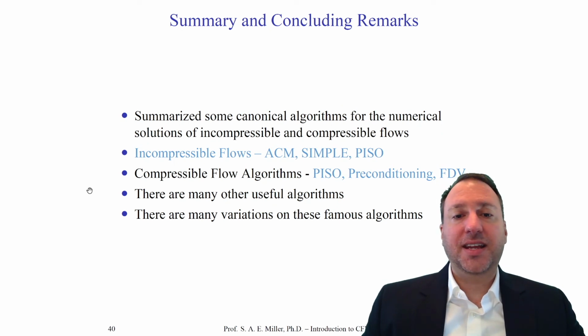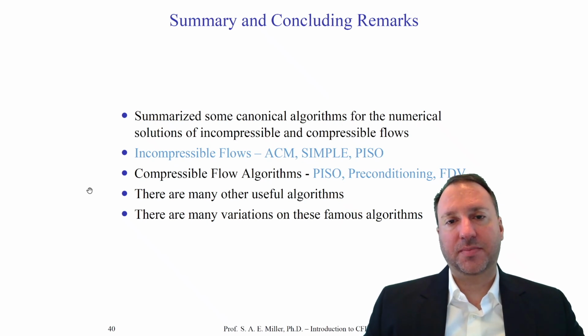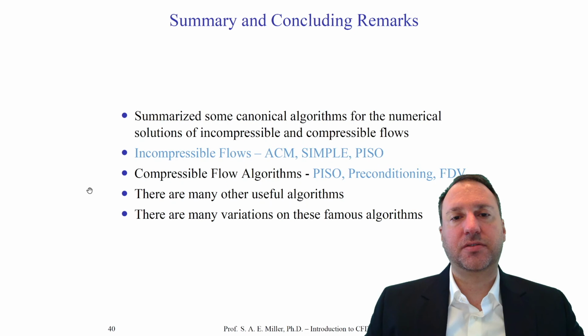Now, there's many other algorithms. In fact, we could have a whole class just talking about all the different types of CFD algorithms. I was careful and just chose 3 or 4 of the most popular ones, which you'll see as choices in the solvers. From this class, try and take away the overall approach and realize what's happening in the solvers and why some of these choices are made. For example, to eliminate the so-called checkerboard problem of pressure in incompressible flows, or to handle seamlessly the different types of dominant terms of convection and diffusion in a high-speed turbulent boundary layer.